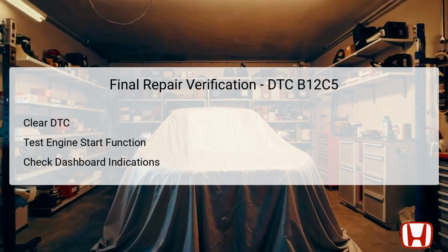This includes verifying that the engine starts smoothly and responds correctly to subsequent presses of the switch. Also, monitor the dashboard for any warning lights related to engine functions. Confirming that all indicators are normal will affirm the effectiveness of the repairs undertaken for DTC B12C5.